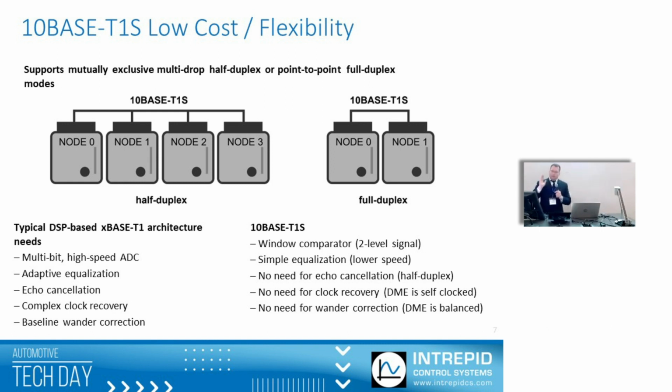But in this case, you might think that having a bus topology would be in conflict with the addressing, but it's not. Essentially, all the nodes on a 10BASE-T1S network must have their own unique MAC address, just like every other Ethernet node. There's no difference. They can optionally also have their own unique IP address if IP is used on a network. But remember, IP is optional. It's not required. MAC address, physical addressing, is required. Every node will have its own MAC address.